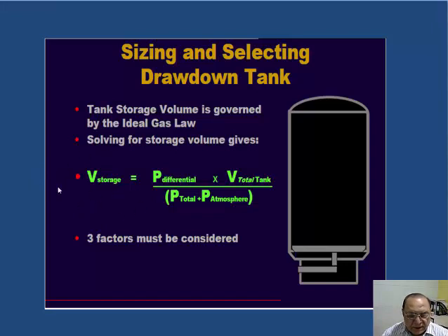The storage capacity is roughly 2 to 3 minutes of the smallest pump's flow, because the pumps are rated with a minimum number of cut-ins and cut-outs according to their horsepower rating and the manufacturer's recommendation. Following those things will save a motor's life.